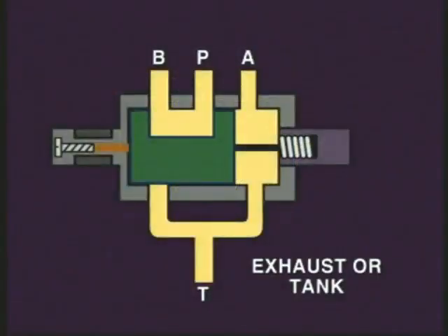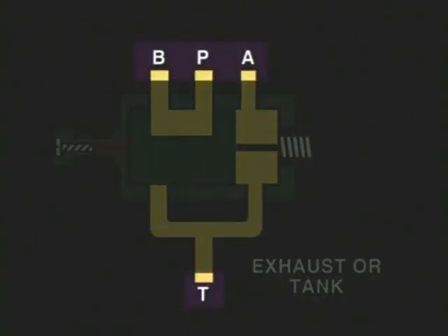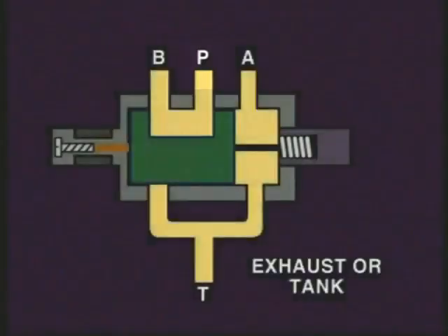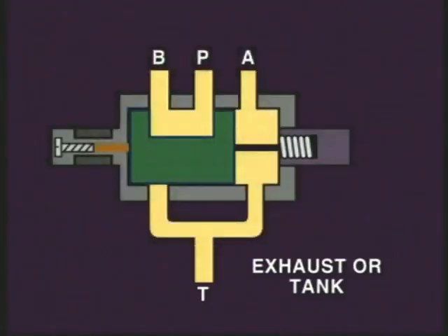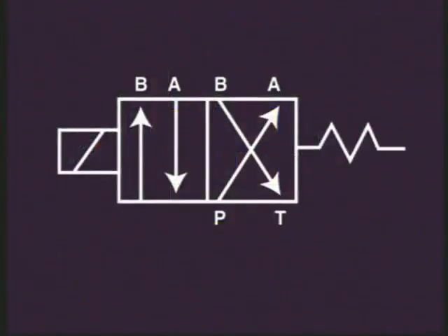A solenoid valve is said to have inlets and outlet ports. Inlets can also be called pressure ports because that's where the pressure oil or air of a hydraulic or pneumatic equipment is connected. Some outlets can be called exhaust ports for air or tank for oil, where the release pressure is directed from, for example, a piston cylinder.